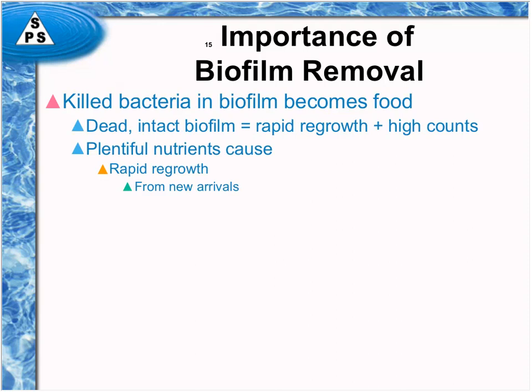And the organisms that are utilizing it or regrowing could be new arrivals coming into the system as soon as the sanitizing conditions are gone, or it could be survivors from the unkilled biofilm that's present, and probably both are happening. And in poorly designed systems, particularly ones that have lots of crevices and flanges and whatnot, where the biofilm is almost impossible to completely kill, it's these survivors that are growing back.